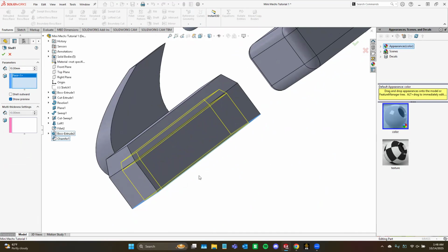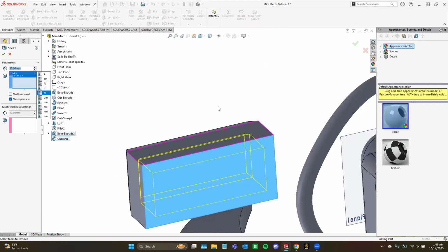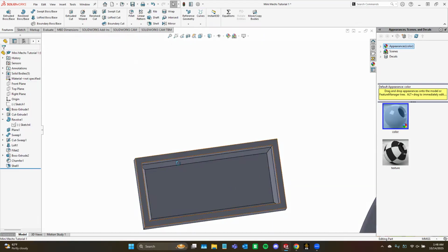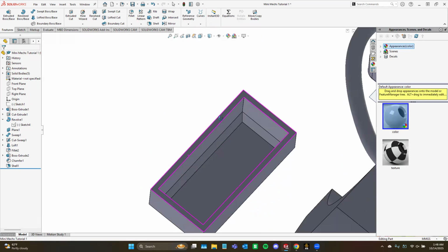That will be especially useful in the CSWA and CSWP, because you're going to have these interesting shapes, and they ask you to hollow them out. So you just select the face, select how thick you want the borders to be. Let's say you want it to be 5 millimeter thickness. Click OK, and you basically just hollow out the inside.